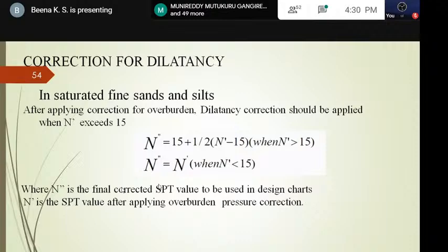So this sand expands, and due to dilation, voids are created in the soil mass. These voids try to suck in water. Since permeability is low, this water does not enter these voids instantaneously. Again, we can go for the undrained condition. So because of these voids and the low permeability, this can create suction head within the soil mass. So negative pore pressure development will be there.